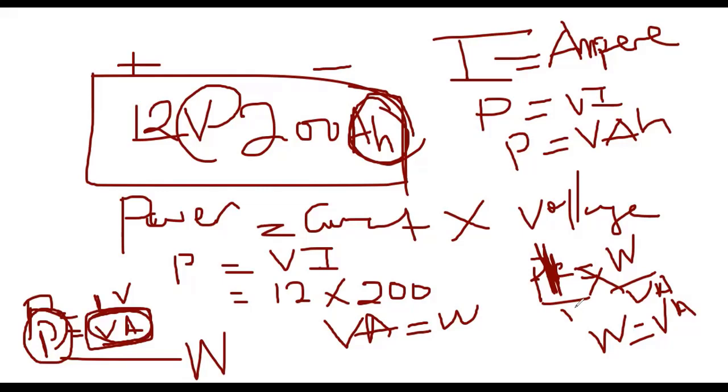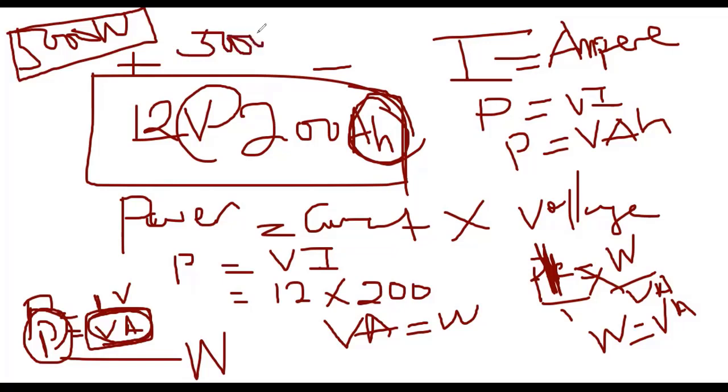But sometimes the people that manufacture inverters rate them, and they can tell you my inverter is 5,000 watts. If a Chinese inverter tells you the inverter is 5,000 watts, be very careful. That means if you do your load audit and you have 5,000 watts, somebody answer this question: are you saying you can put this 5,000 watts on this inverter?